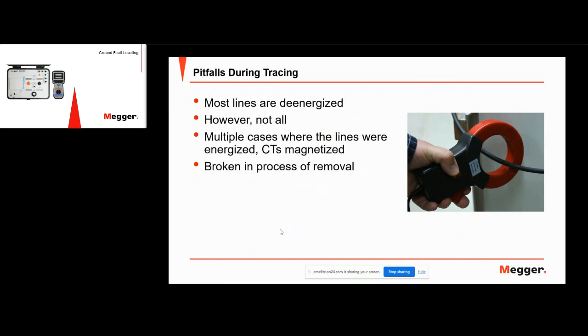Now, as I said, most lines are de-energized. However, that's not always the case. We've had multiple cases where people have put current clamps, AC current clamps, onto energized lines, and they've ended up having to break the current clamp to get it off.